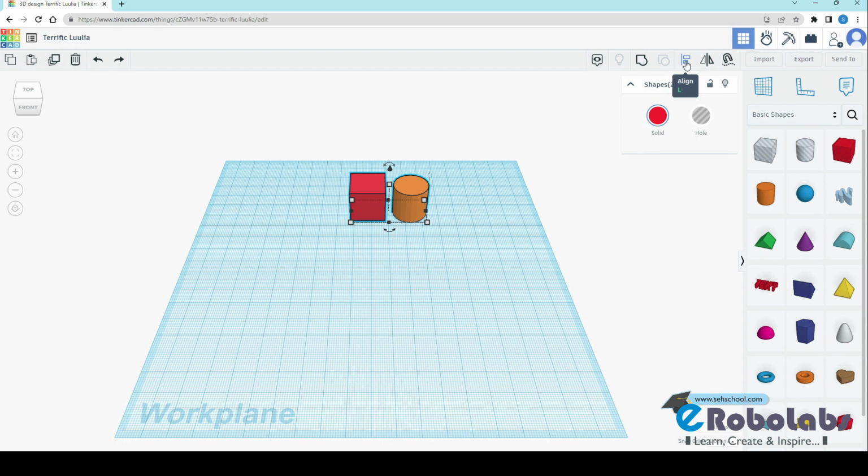Okay. If you see, you can see the two objects selected. The align command has already been selected and the left cube is to be aligned with the right cube along the lower horizontal plane. Like that. You can see the alignment guide planes shown on the screen as black lines with large black dots. So you can align them accordingly, like that.